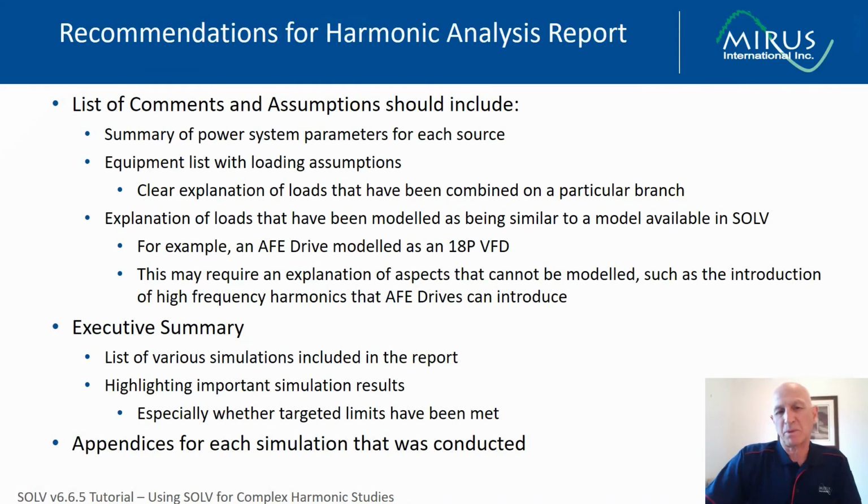For example, in this case, we modeled the AFE drives as 18 pulse VFDs. This may require an explanation as well of aspects that cannot be modeled or that weren't modeled, such as the introduction of high frequency harmonics that AFE drives can introduce.